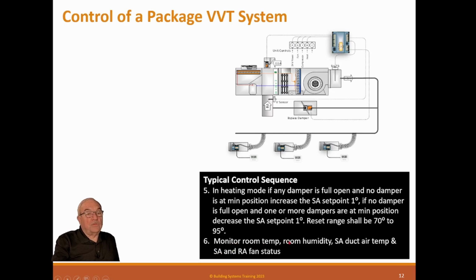Monitor room temperature, room humidity, supply air duct air temperature, supply and return fan status. Now these are simple systems on a package unit, and you have to have this bypass damper on them.